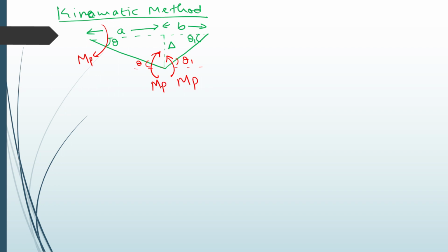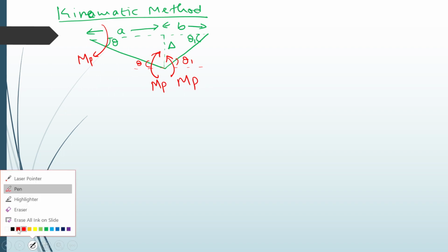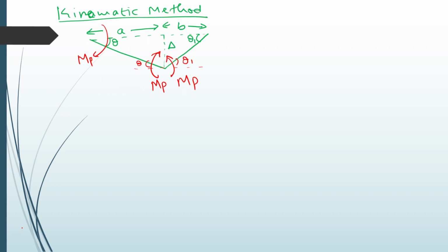The condition is virtual work done: external work done equals internal work done. External work done means load into displacement, and internal work done means moment into rotation.